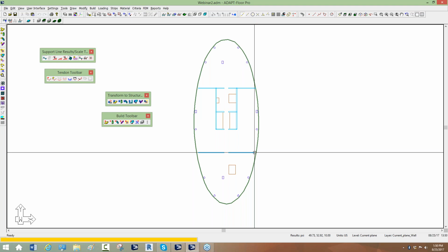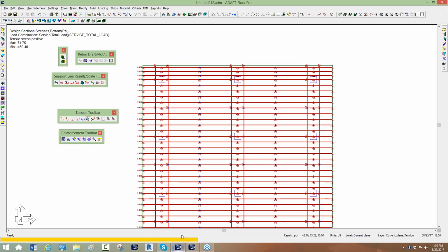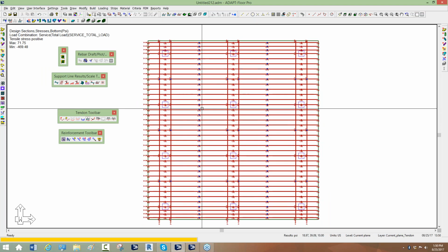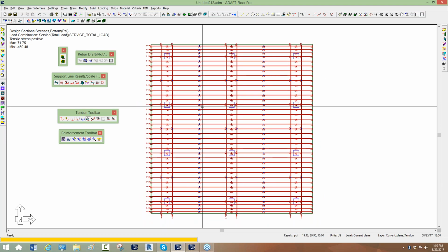And for those of you who are used to the program, I'll show you one thing here. This is the next version of Builder, and similar to the version we're using today, which is version 2016, 2017 requires the user to lay out tendons. You can lay them out just manually. You can lay them out based on mapping. You can send a strip to PTRC and export it back in or import it back into Builder. So assume that you do something to get tendons in the model.